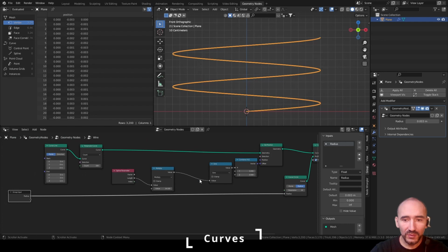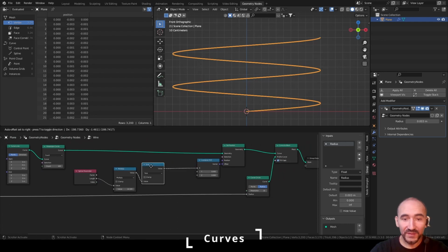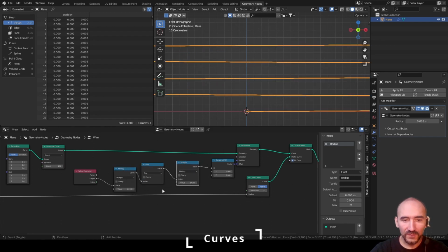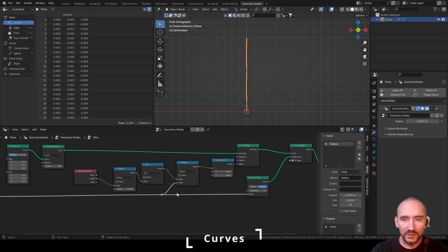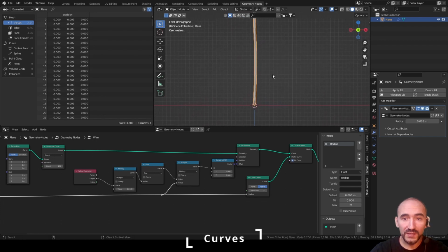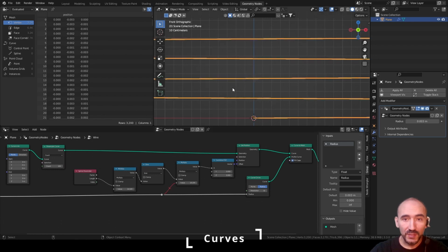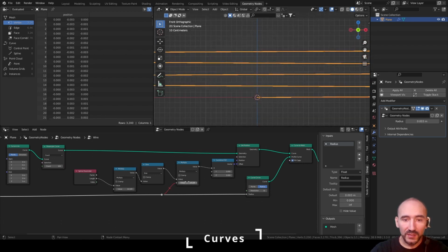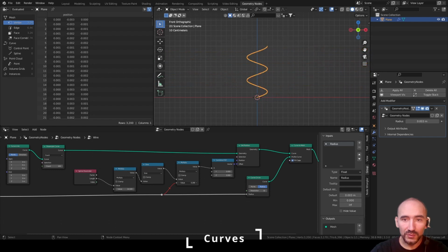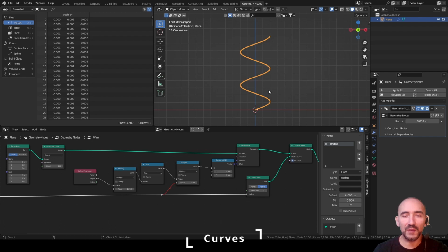Tab to enter the group node, and after the sine we can use Shift D to duplicate this multiply, and Shift right button drag to link this value of radius to shrink the shape of this sine. Now if I press Ctrl Alt right button drag, I mute this value for a moment. I can touch this value as I want. You have to have a base number of values that you can manipulate with a coefficient in your project. You have to try to get a normalized value.